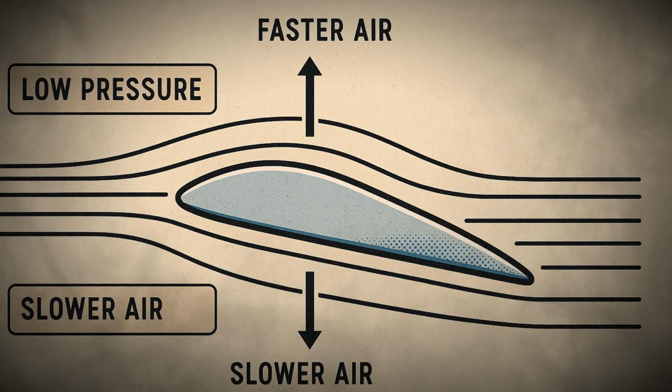The horizontal stabilizer prevents unwanted up and down motion, known as pitch. Attached to it are the elevators, which control pitch by moving up or down, raising or lowering the airplane's nose. In some modern aircraft, the horizontal stabilizer is designed as an all-moving surface known as a stabilator, which improves control at higher speeds. The tail also plays a crucial role in maintaining balance.